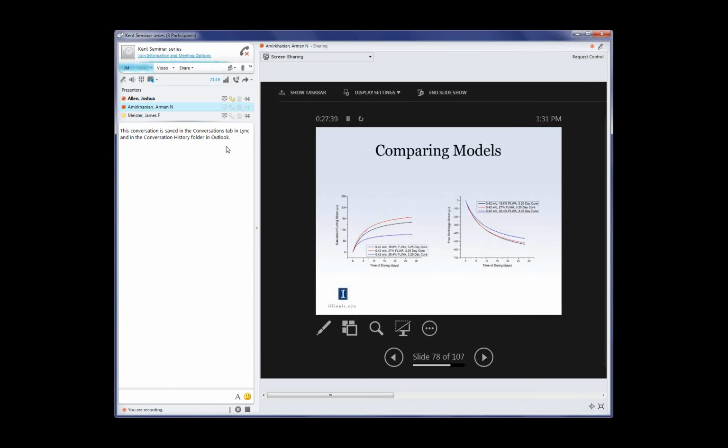All right. And same thing here. We have our 18%, 27% lightweight sitting around here. They're also grouped right there with a higher or stronger free drying shrinkage strain, stronger curling. And the mix with 35% lightweight has the least amount of curling and the least amount of free drying shrinkage. So the shrinkage model also helped us conclude that the drying rate, or the loss of water in the pores, is very strongly tied to the curling that we see here.